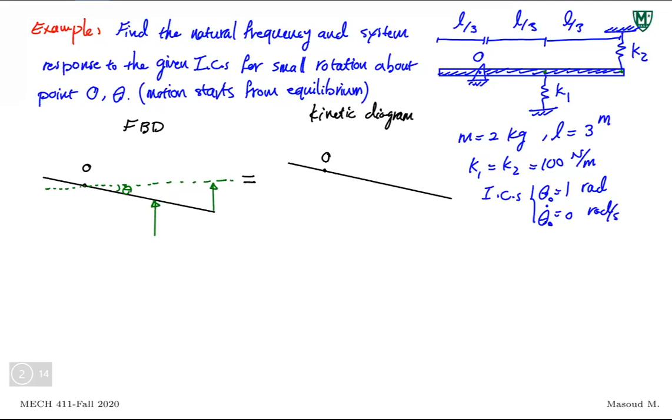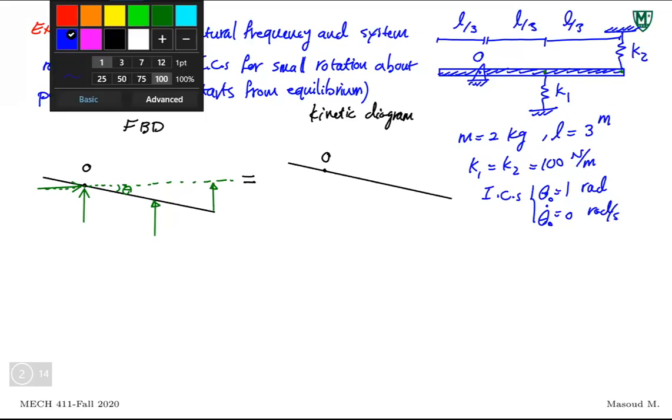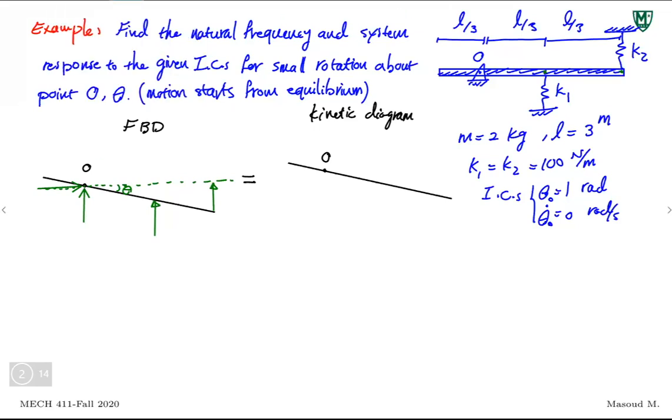Before I go further with the spring, are there other forces on this bar? Reaction force to the support. Yeah, I have reaction forces, right? For those, I'll just put them right there and there. You'll see they're not that important the way we're going to analyze the system, but it makes sure that the free body diagram is complete. Assuming that this is X and this is Y, my coordinate system, I'll call this OY, and I'll call this OX.